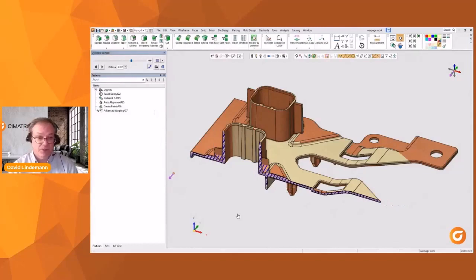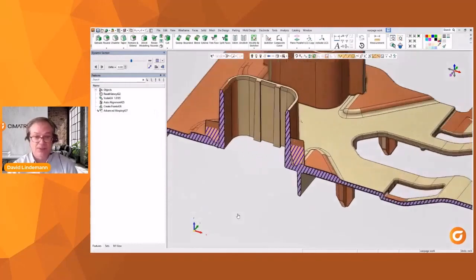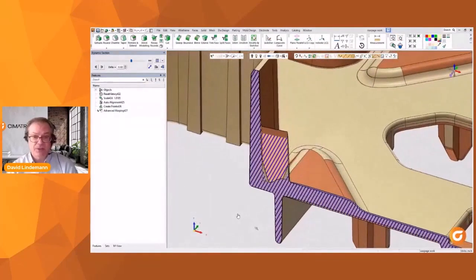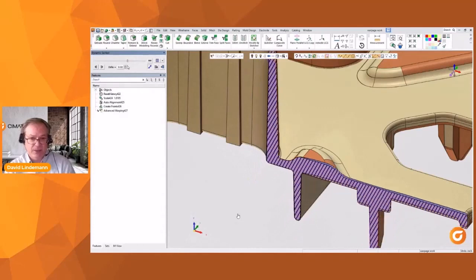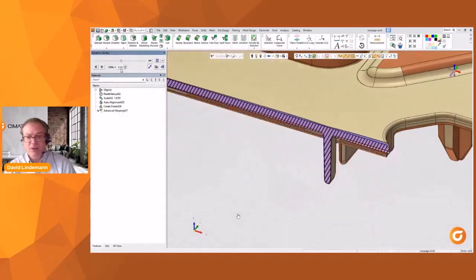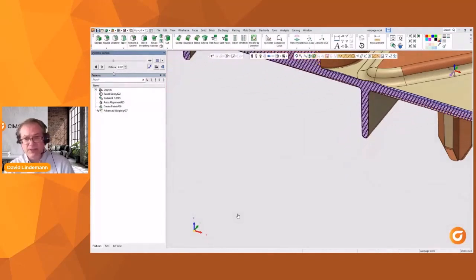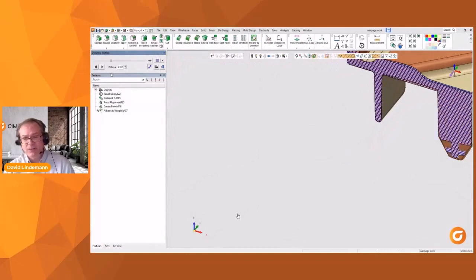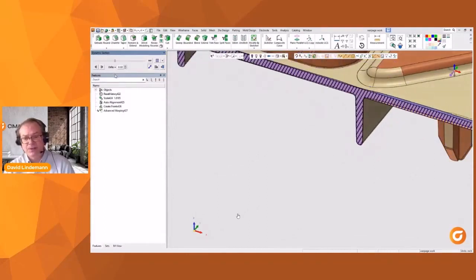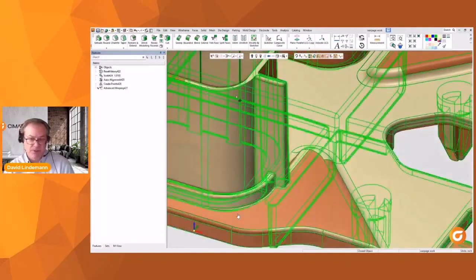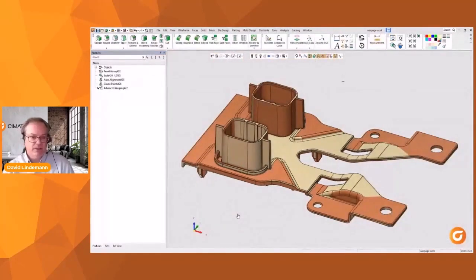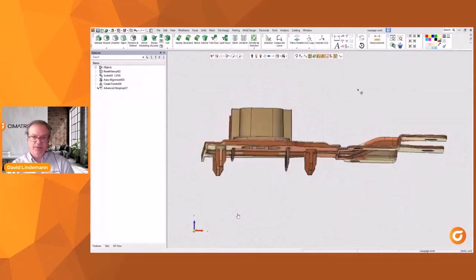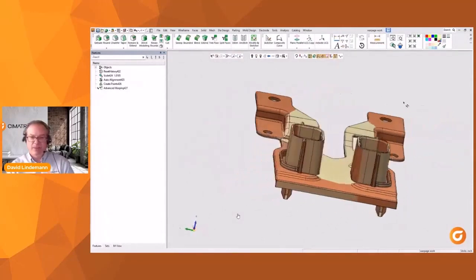Do I want to keep my rounds perfectly round? I would check for roundness. Exactly. Especially if it's something like in a side pull, I would take a close look at maybe adjusting that to a standard round situation. Okay, well, how do I make these little tweaks? Now, here dragging through, I'm still looking at the wall thicknesses, and you can see like the near verticals, everything drafts out nicely. So the new draft I have is very comparable to the original draft. So I'd be very happy with that.